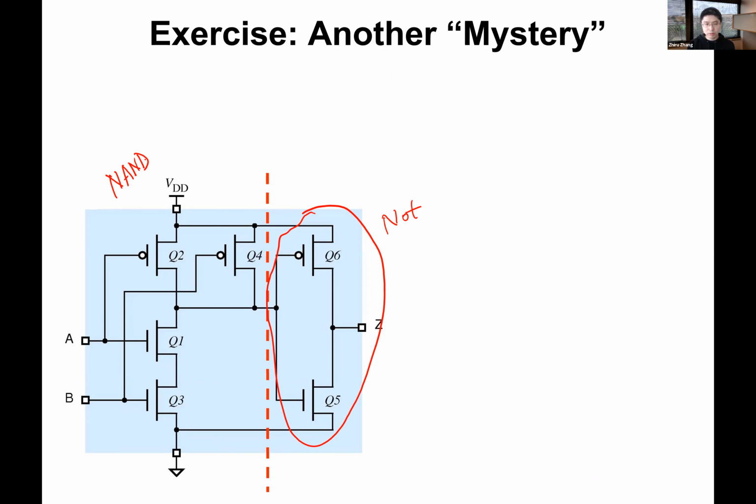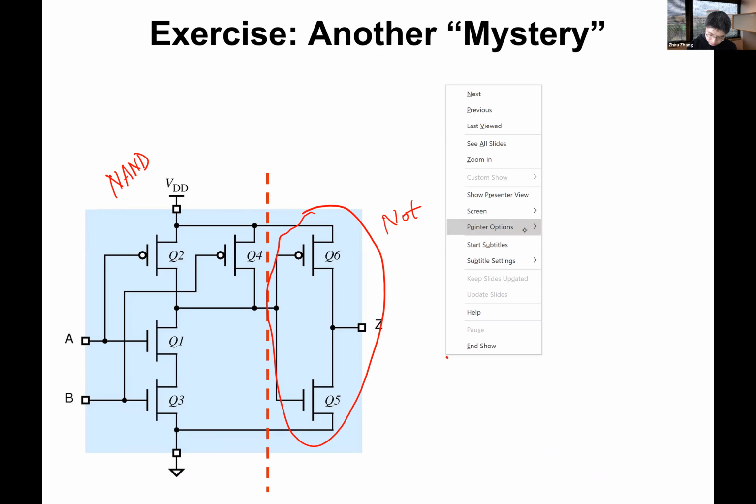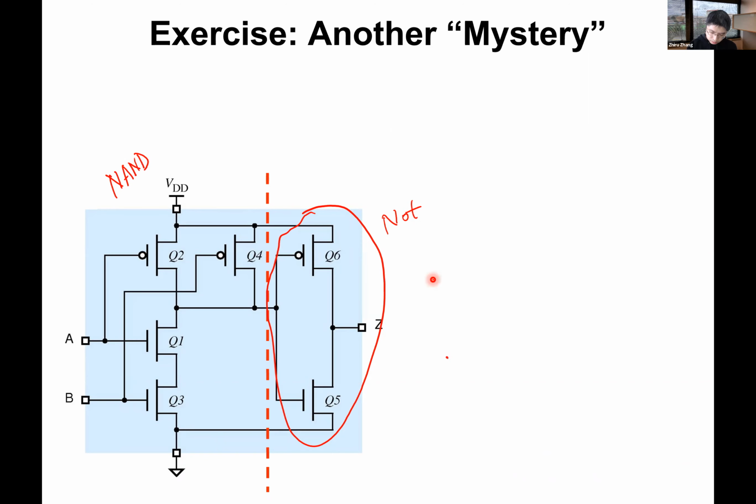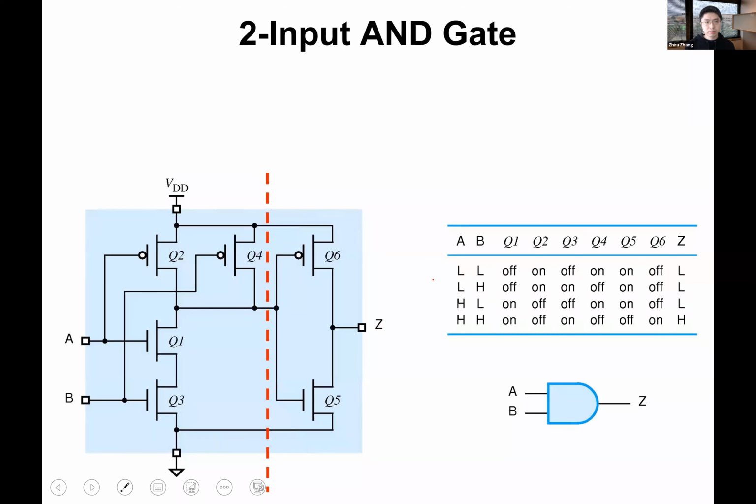It seems sort of convoluted, right? This whole thing is basically an AND gate. Hopefully this is interesting to you, right? If you want to implement an AND gate using CMOS, we actually have to do this. So this is actually more expensive than NAND.